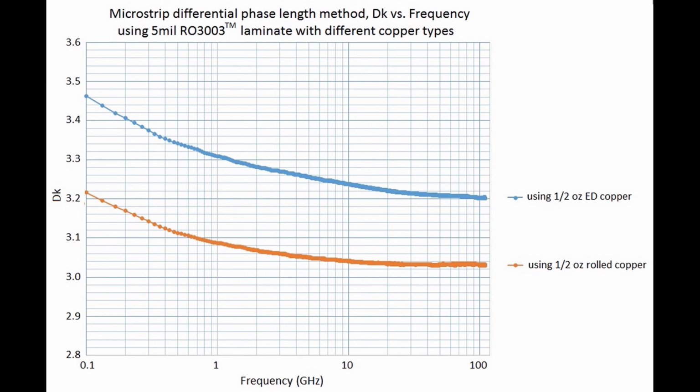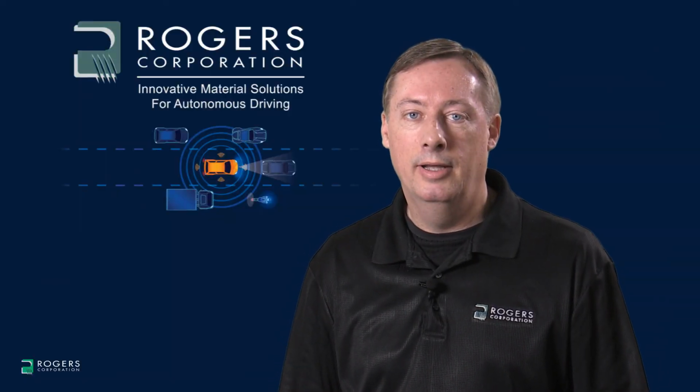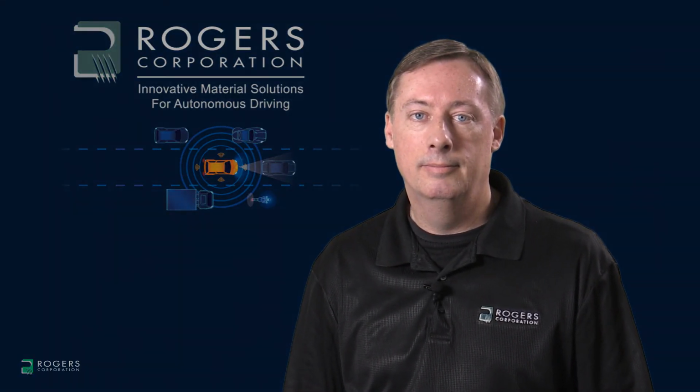At 77 gigahertz, the design Dk for the ED copper version is about 3.16. At 77 gigahertz, the version with the rolled copper, which is very smooth, has a design Dk of about 3.03. So you can see that with the very smooth copper, even though it's a thin substrate and sensitive to copper effects, the copper is really not affecting the phase velocity much. The circuit really is perceiving the bulk or intrinsic Dk of the material of about 3.0. This now concludes this video for design Dk considerations. Thank you for watching.